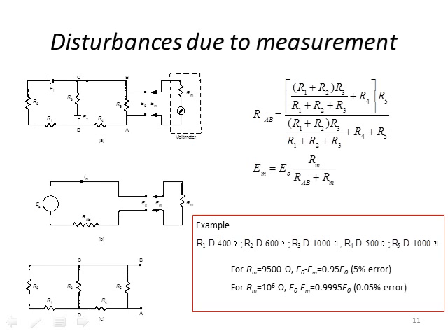The lower left circuit shows the equivalent impedance RAB between terminals A and B, where the voltage sources have been shorted. And then we can simply series connect R1, R2, which is in parallel with R3, which is in series with R4, which is in parallel with R5. And then you construct RAB in the center circuit diagram.